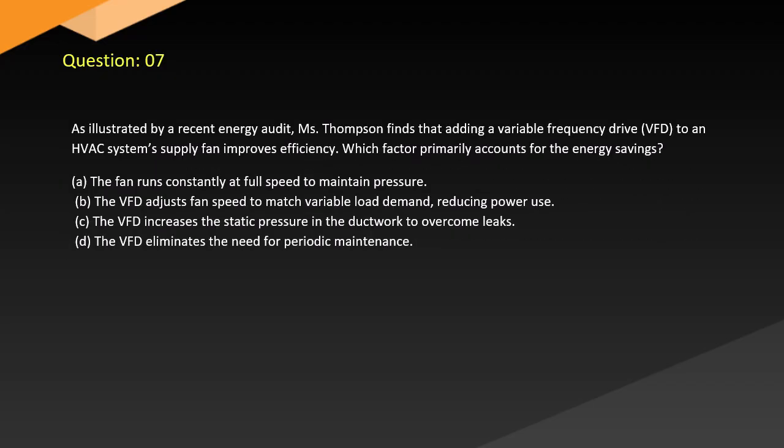Question 7. As illustrated by a recent energy audit, Thompson finds that adding a variable frequency drive (VFD) to an HVAC system supply fan improves efficiency. Which factor primarily accounts for the energy savings? A. The fan runs constantly at full speed to maintain pressure. B. The VFD adjusts fan speed to match variable load demand, reducing power use.